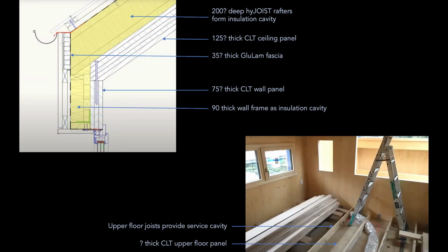Here's a 2-storey home with essentially 2 homes worth of wood in it. So one house worth is in the CLT. Unfortunately, it's spruce. There's a house in Tasmania. And another is in stick framing, which also looks to be of spruce. It sits alongside the CLT to provide those cavities we need for thermal insulation and for services. If only the upper floor joists and the roof rafters were beefed up just a whisker, there'd be no structural and no thermal purpose to the CLT whatsoever.